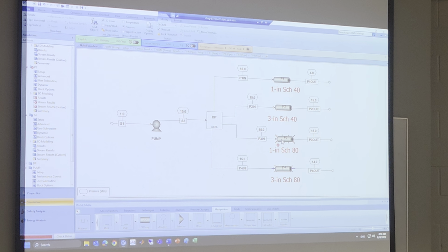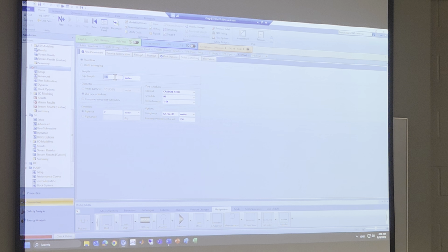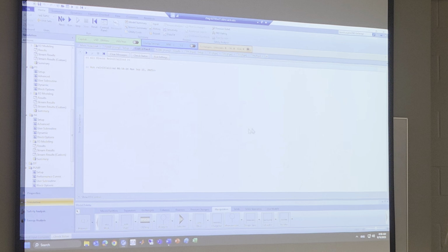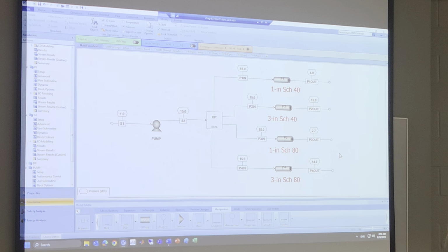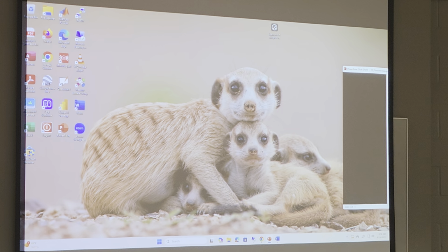Can we make this pipe 3? Maybe I can choose like 70 meter, let's try. Whether it works. It may work, but you will experience a huge amount of pressure drop. Maybe so. It's like 12.3 atm pressure drop is not that good design. So please play around. Okay? Not that difficult. But now the question starting.